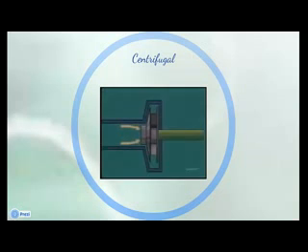Impellers are also classified as single or double suction. With single suction impellers, fluid can enter only one of the impeller's sides. That can cause problems such as unbalanced thrusts in the direction of the suction. In high volume or high discharge pressure pumps, that problem can be serious.